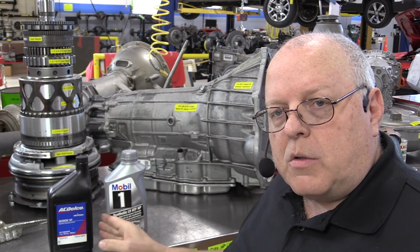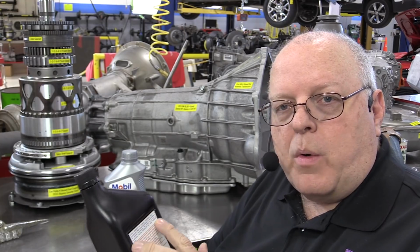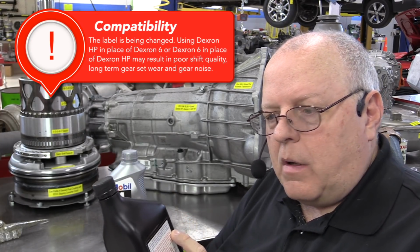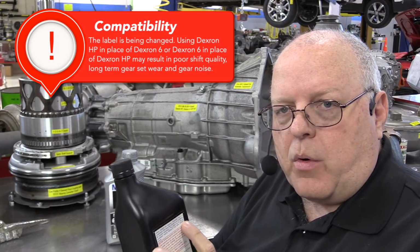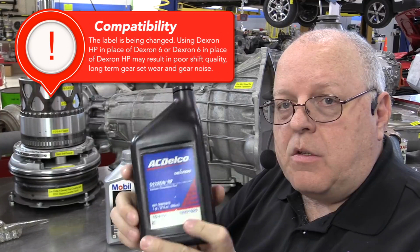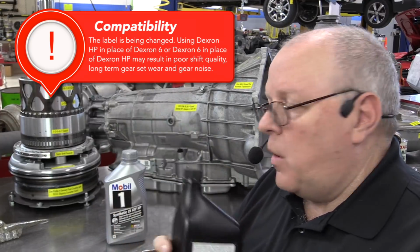Now, both of the bottles of Dexron HP fluid here say on the back that it's compatible with earlier versions of Dexron fluid. That is incorrect. It is not compatible with earlier versions of Dexron fluid. They made a whole bunch of these with the wrong information on the label.